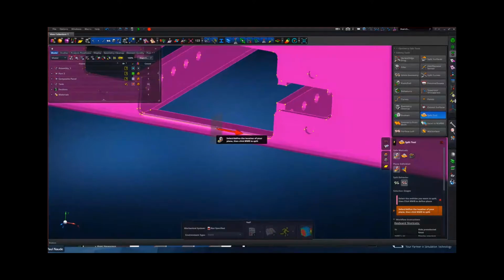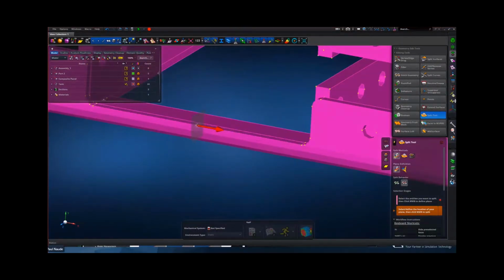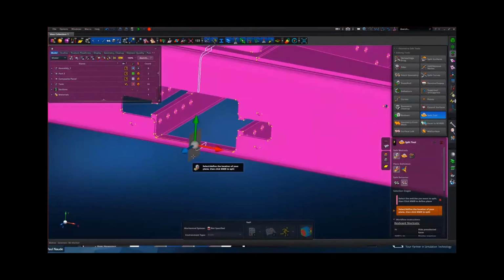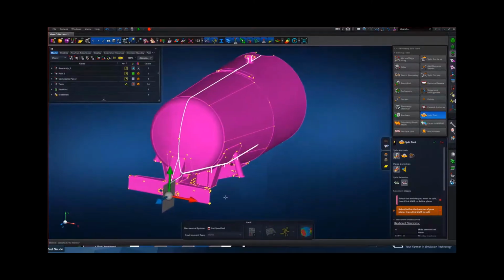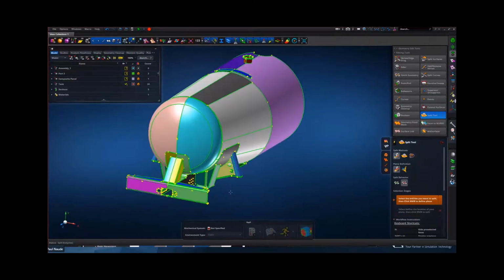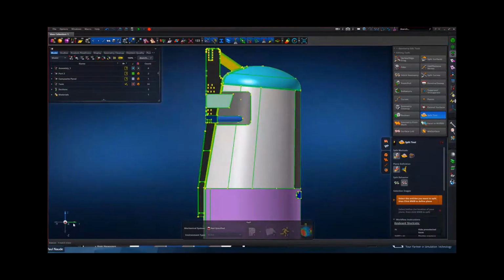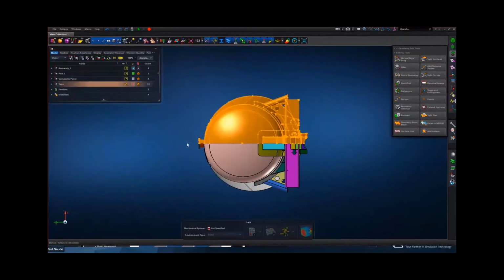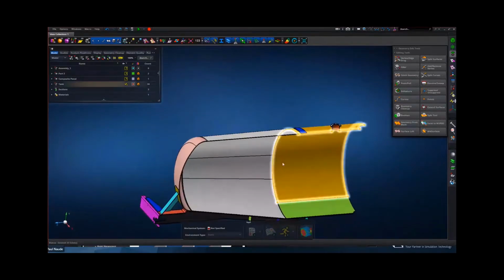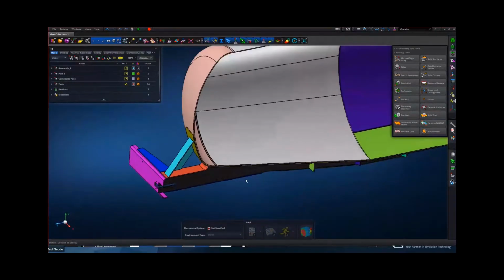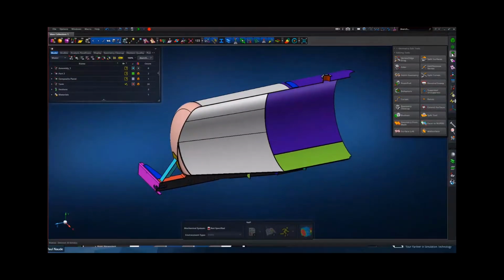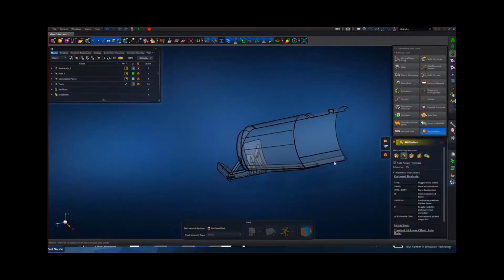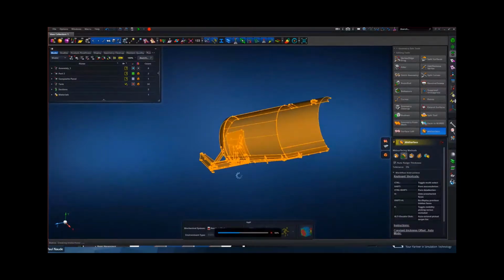And I'll select a middle here. And if you noticed, anytime you hover your mouse for a moment on any feature, there's a little white dot that appears. That is the absolute middle. So you don't have to find or know exactly where the middle is. You can find it on the fly. And now we have a model where we have everything split nicely in half. So I'm just going to delete this half and work on this half to showcase some of the tools that we want to show. So I'll again quickly generate the mid-surface using the automatic thickness for constant thickness properties.